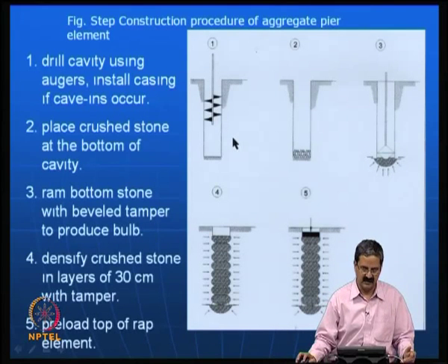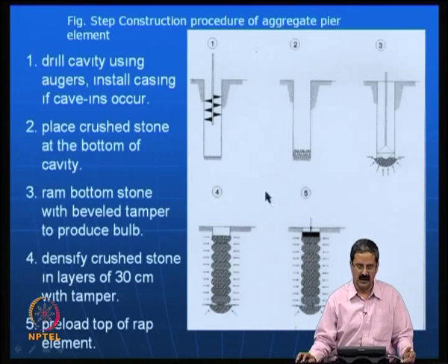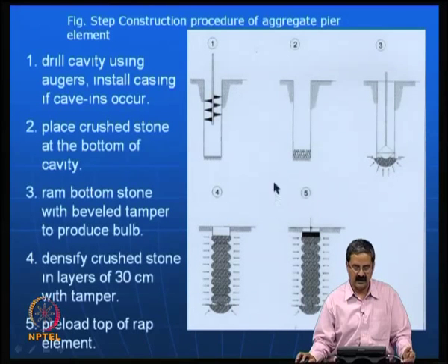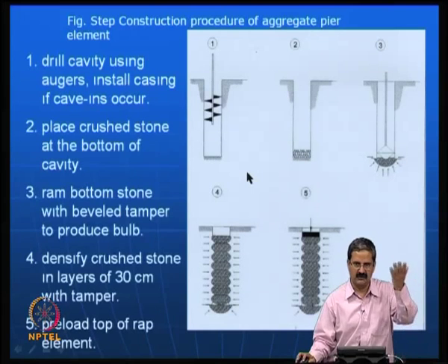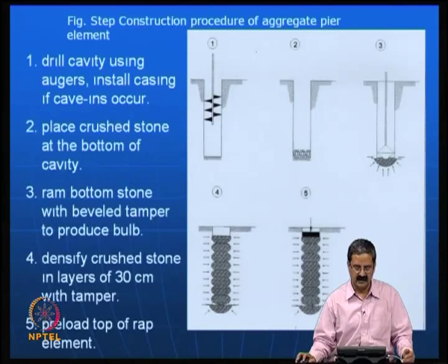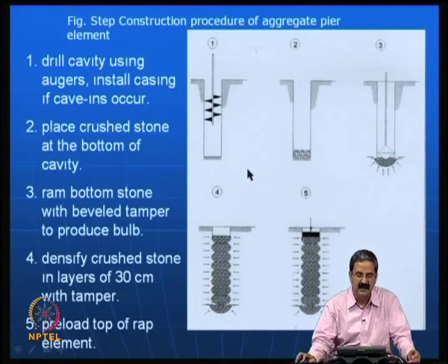I mean, this is what I find, you have to calculate some of these things properly and check some quality control. I may not follow any standard method, but I am very sure that this method works. So, you should be very careful in doing these operations, and in design also, like proper length, spacing and depth. The depth depends on the significant zone of influence, and spacing and other variables one can calculate, and do a parametric study. It is called an aggregate pier, and it is quite simple.